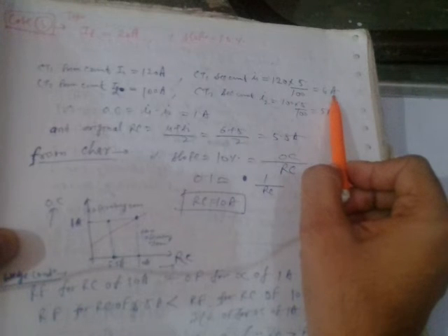Now let us say in case number 3, let us take a fault current of 20 ampere, and let us say the percentage slope is 10%. So the current seen by the CT1 primary is 120 ampere. Why 120? Because our assumption is that 100 ampere goes to load. So the CT1 secondary current is 120 into 5 by 100, that is the CT ratio, so 6 ampere. CT1 secondary current I1 is 6 ampere.